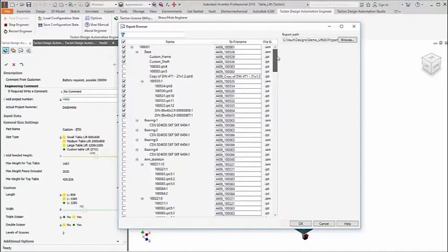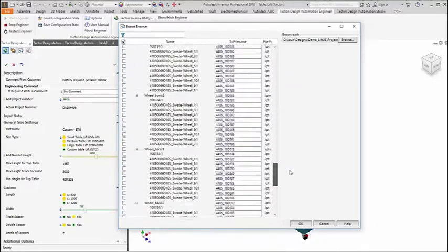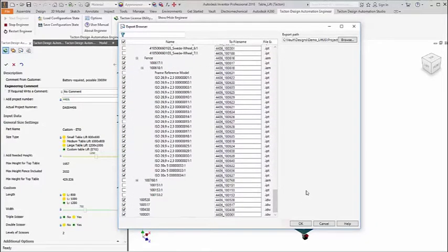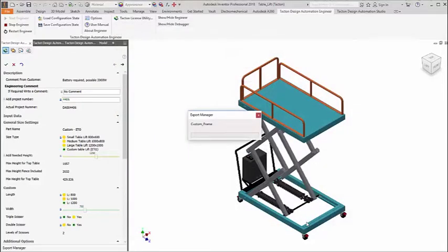And those are the ones that are custom, in other words, are new parts. You can also see down here that you will get new drawings. In the upper right corner, you can set the path. Now the path is already set to the correct folder, but otherwise you can choose a new one through the browser, or just change the number if you know the exact position. So let's export.